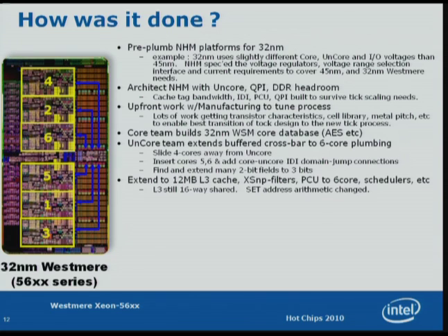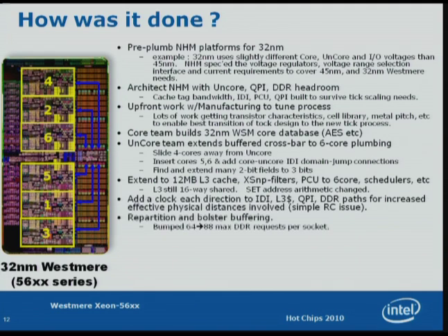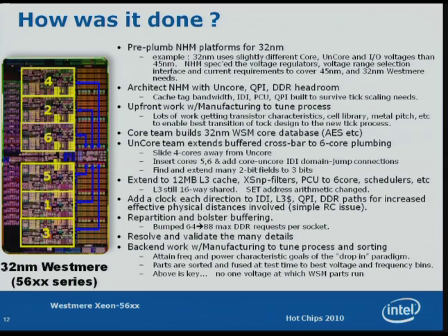That needed to be changed to a non-power of 2 arithmetic there. Okay. The rest of it, there were clocks that had to be added here because of the additional physical distances. Again, this part is slightly smaller than the old one, but when you talk about the movement to the new process, the RCs and so forth don't scale perfectly, so there were clocks that needed to be added, and then we talked about the buffering that needed to be added.